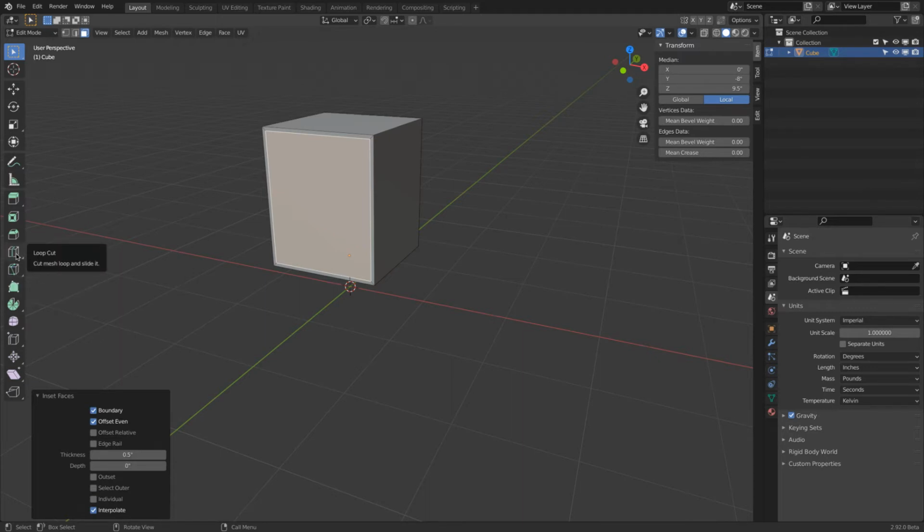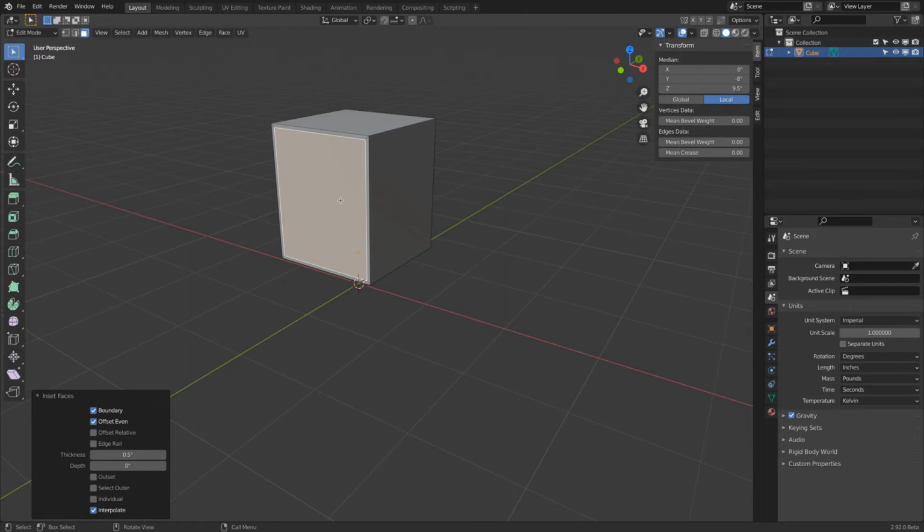And the loop cut is actually, the command is Control R. And the knife command is K. K like knife, and loop cut, well, Control R. Okay, so how this works, I will show. Control R. There you see it creates a loop. And when I click and I move this one up or down and then click, you see it added a loop cut. And this actually goes completely around.